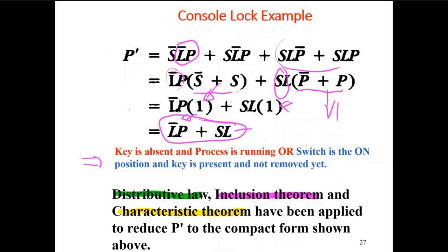Now, every console in CNC machine and robotics or whatever sensitive processes have a console with this type of arrangement. Now, you have three inputs here. It can be a lot more. Okay? For example, in my robot console, on the surface or on the console, there are about 16 or 17 switches. But inside, there are many more. There are close to about 484 inputs and outputs combination that are primarily triggering alarms. If one of the motors is down, well, it'll come up on the panel. So there are a lot more inside where these equations are not going to be as simple as what I have shown.